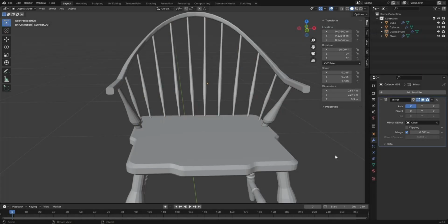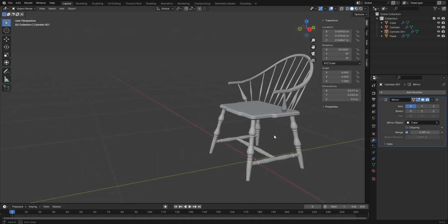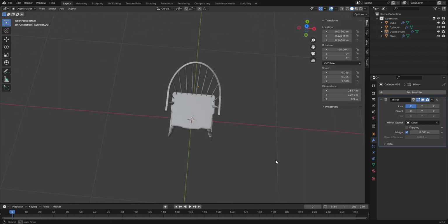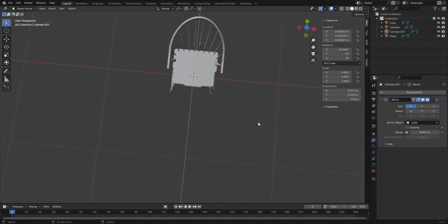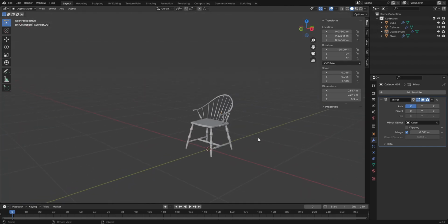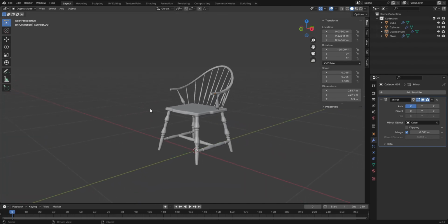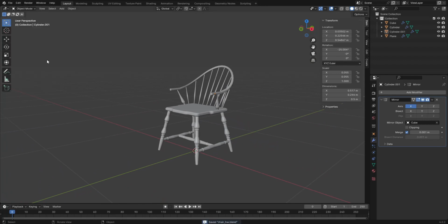On my screen you can now see a new chair, which does have a little bit more details. With exception of the backrest, I did only use tools we have already learned. All the ornaments were done by adding additional edge loops and then scaling them as needed. The rounded edges on the seat were done with the bevel tool. The style of the backrest could be achieved by using proportional editing. First, bend it backwards like we did earlier, and afterwards bend it upwards.